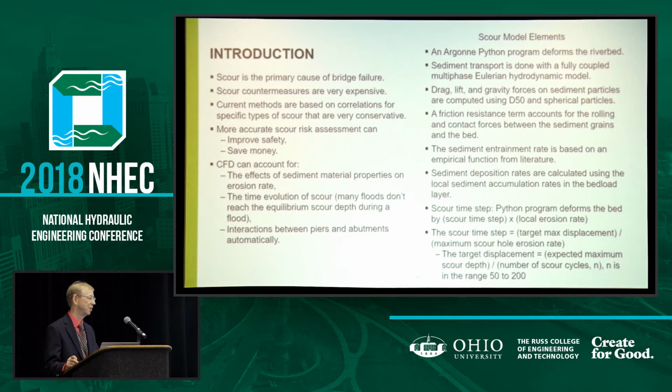That's where you kind of treat the particles in aggregate, and you have basically 4 partial differential equations to solve if you have a single size. There's 3 components of velocity and then the mass conservation. The other alternative was to track individual particles. That's called a Lagrangian method, and you're solving ordinary differential equations to do that.